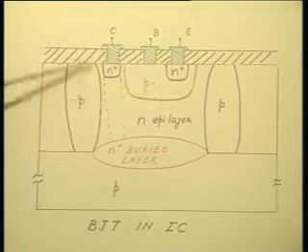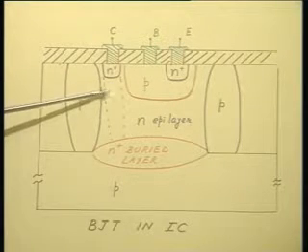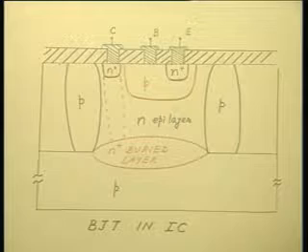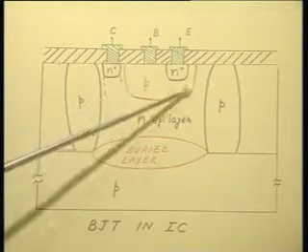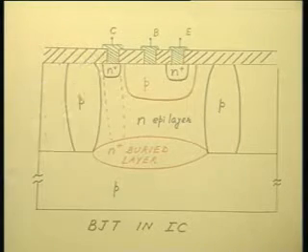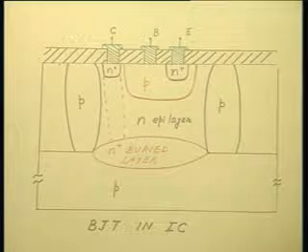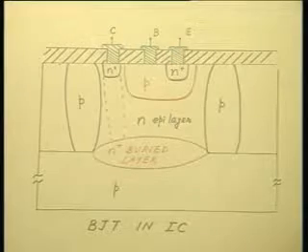You do not want it to be effective. How can you suppress it? By suppressing its gain. How do you suppress its gain? By increasing the base width. This is a lateral transistor PNP. So, this is its base, right. That means the base of your actual transistor should be a considerable distance away from the isolation P tub in order to keep the base width of the parasitic PNP transistor large.